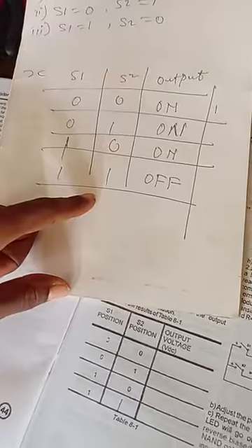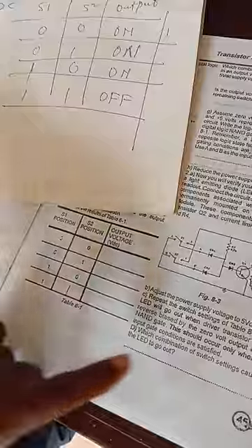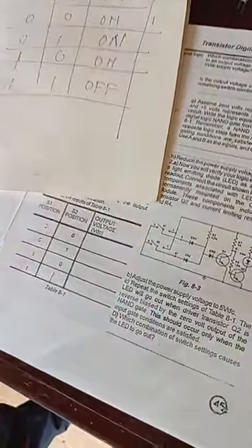Okay, which of the combinations, look, no mistake, I'm sorry. Which combination of the switch setting causes the LED to go out? Okay, it's only when we have switch 1 at 1, switch 2 at 1. That's what makes the LED go out. They don't say to go on, but to go off. That's what they are talking about. It's only one combination, which is S1 to be 1, S2 to be 1. That's when the LED will go out. That's our question 2D. We are done with that.